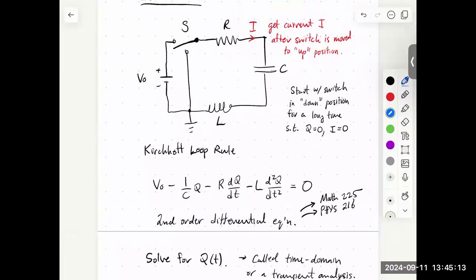And you almost always have that, even if you don't explicitly put an inductor and a capacitor in your circuit. Let's imagine you didn't put an inductor here. Your circuit still has a loop and it still has a current going around that loop. So there's still some parasitic inductance involved in your circuit, and so this would still have a resonance frequency.